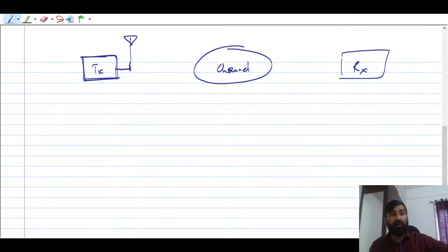So how can we solve this problem? This was a problem earlier. What you can do here is take your message signal, which is at low frequency, or low bandwidth. The message signal will always have low bandwidth. Sometimes we call it the baseband signal, remember that. Now what will happen? We will bring some sort of carrier, and the carrier is nothing but a high-frequency signal. We take the message signal and the carrier signal and multiply them. The carrier will be in the form of cosine, sinusoidal or exponential.